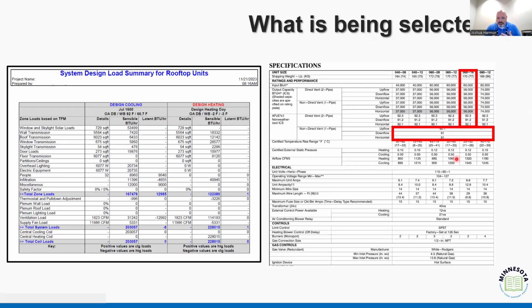And that's what frustrates me as a building official or as an inspector in the field, because you design this system to work based on X piece of equipment. But when we get out in the field, because we didn't document the design properly, I now have flex duct where round duct was designed. Well, yeah, it's still a circle, but it's not a circle that we're looking for. It's the interior surfaces and how they affect airflow.